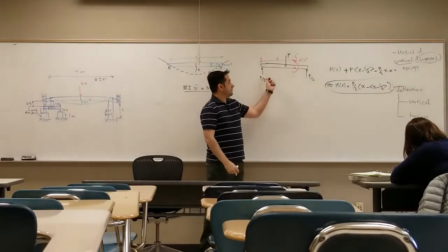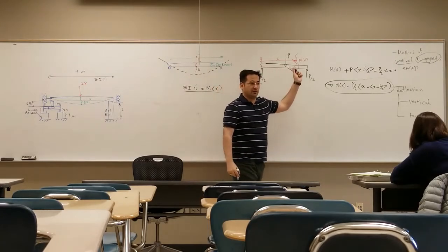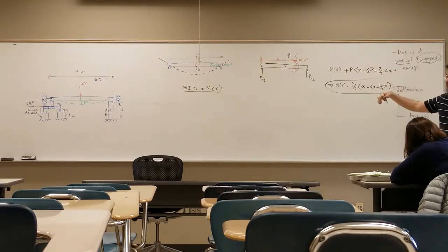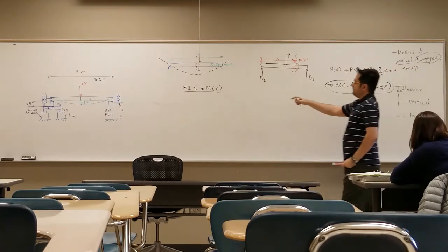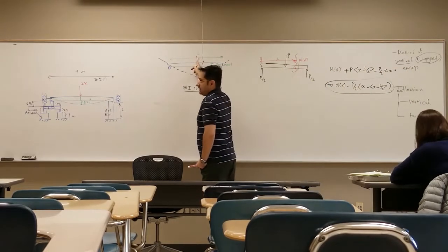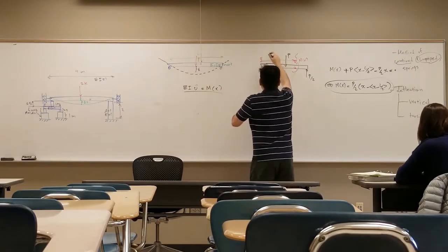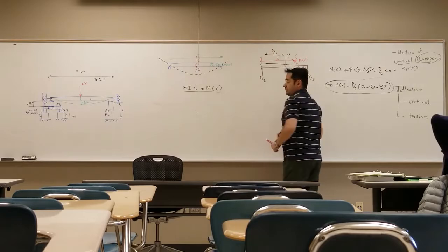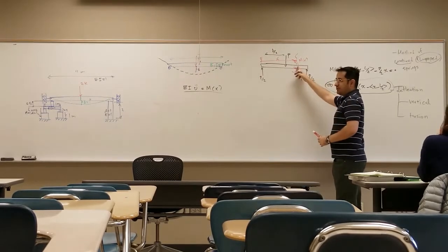Again, as you can see, this P is going to be distributed in half, so you can get that from symmetry. I didn't write summation of forces in y or summation of moment. When you have P symmetric at the middle, it's L over 2 from here to here, and this is P over 2, P over 2. Then I write the moment equation at this point.